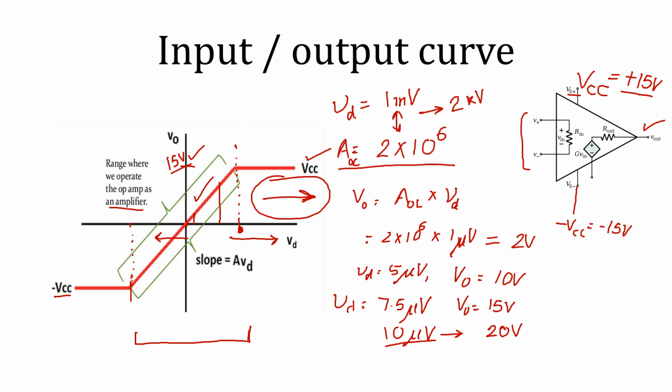Okay, so we are not in the amplification region. To make this functionality work in the practical scenario, when the difference voltage is not very small, sometimes it is millivolt, sometimes 100 microvolt, we need to modify the open loop gain, and for that the scientists have proposed that this can be easily used in closed loop mode. We will discuss later how we can redesign the same IC.